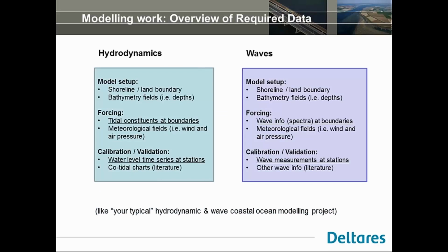This slide gives an overview of the typical data sets that you require for such a model development. Here I mentioned both hydrodynamics and waves. You see the similarity. Basically, you need the data sets for model setup. So you want to start with your shoreline information, also bathymetry fields. Then you need to define the forcing.